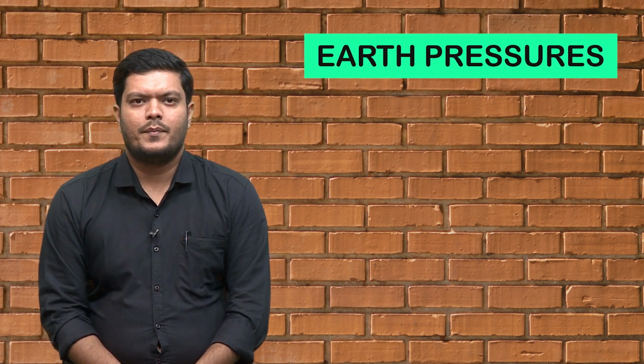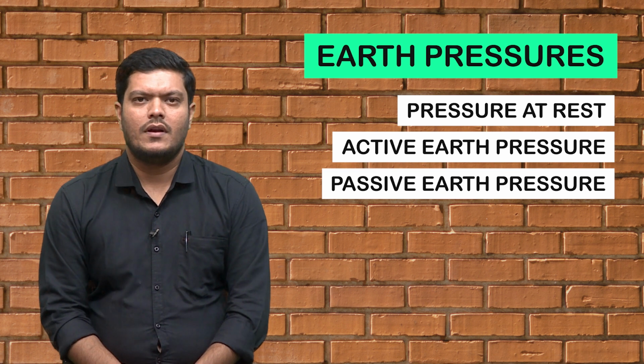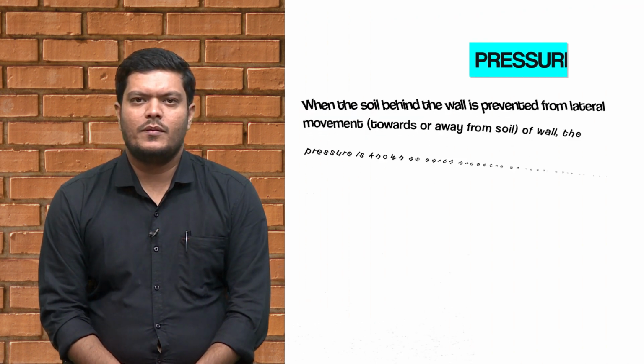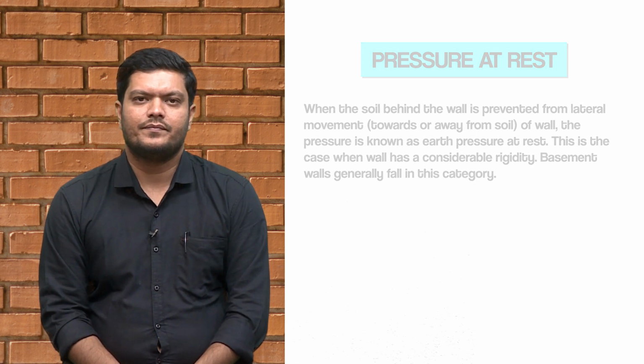Earth pressure: pressure at rest, active earth pressure, passive earth pressure. Pressure at rest: when the soil behind the wall is prevented from lateral movement toward or away from the soil or wall, the pressure is known as earth pressure at rest. This is the case when the wall is considerably rigid. Basement walls generally fall in this category.